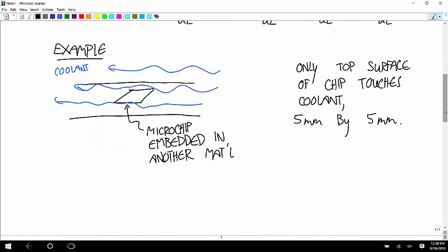So what type of heat transfer are we talking about here? That's convection, yeah, because the fluid's moving across. So heat is being transferred from the top of the chip to the coolant, and then the coolant particles are physically moving that heat away. It isn't transferring away from the chip particle to particle through energy. Those particles themselves are actually moving away. So this is convection.